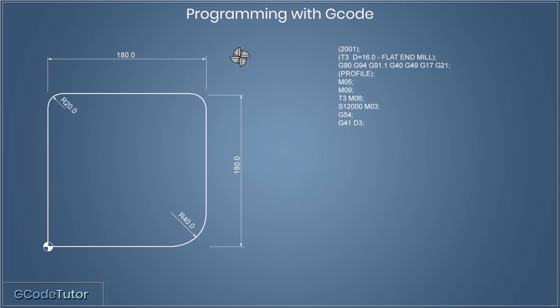Now here we have G41. G41 adds cutter compensation, so the cutter goes to the left of the component, whereas G42 would be right cutter compensation, so it would go to the right of the component that we are cutting. The D3 is the section of code here where we call upon the tool table offset. So this tells the machine to call the tool information from table 3 on our tool table, which also gives the diameter or radius of our tool.